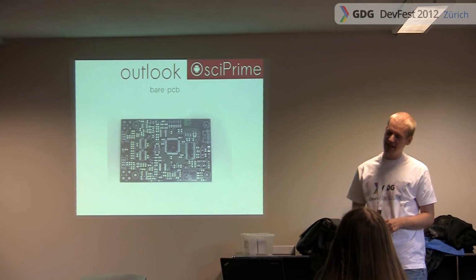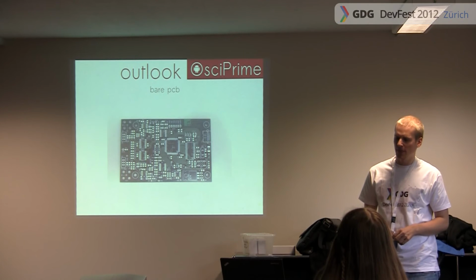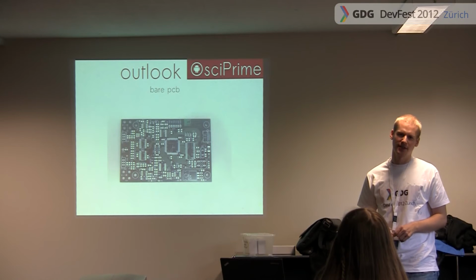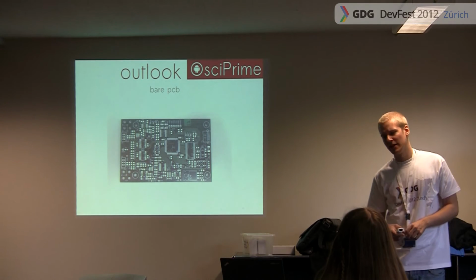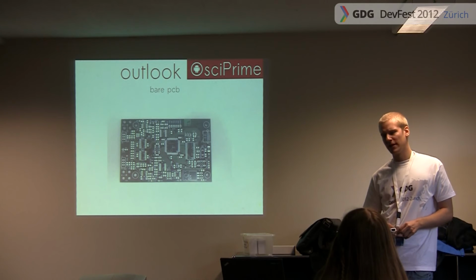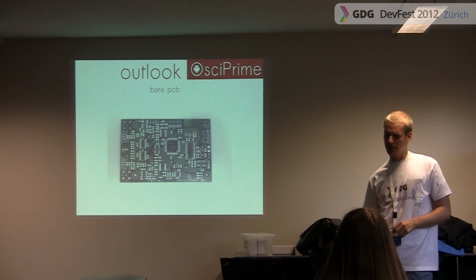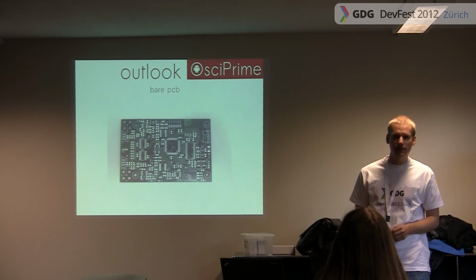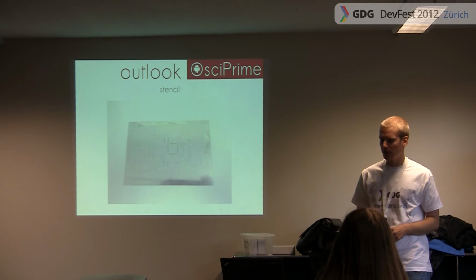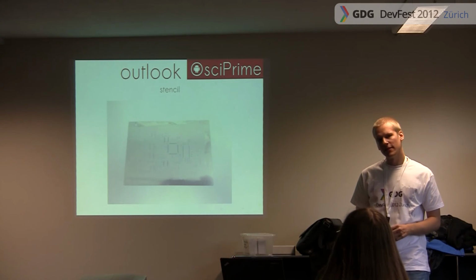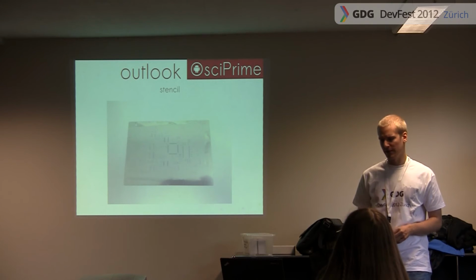What you need for that is of course a bare PCB. For instance, you can order this at PCBpool.com or Beta Layout, I think it's called. If you do just one, it will be maybe 60 euro, but if you want to make 3 or 4, prices go down. That's pretty good. And what you also get at PCB pool is a free stencil. The stencil, as you can see, is a small plate, and it has openings where the footprints of the components will be.